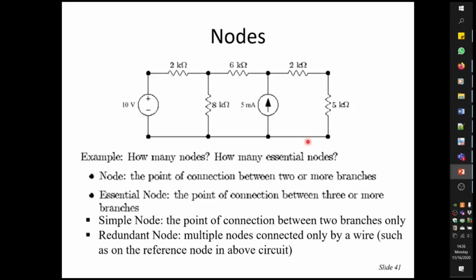So that is why, when we draw and analyze circuits, we typically think of the bottommost node as the reference node. But that is strictly not the only possibility. You may as well consider any of these 5 nodes as the reference node and write out the potentials or voltages of the other nodes with respect to that chosen reference node. It's really up to you.